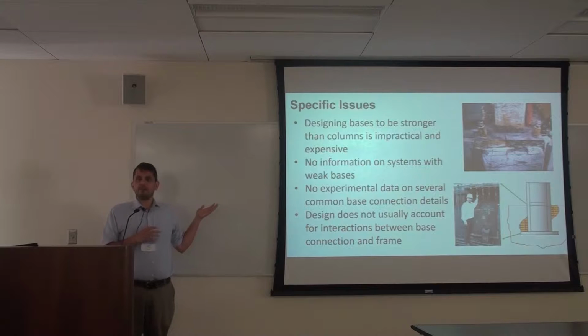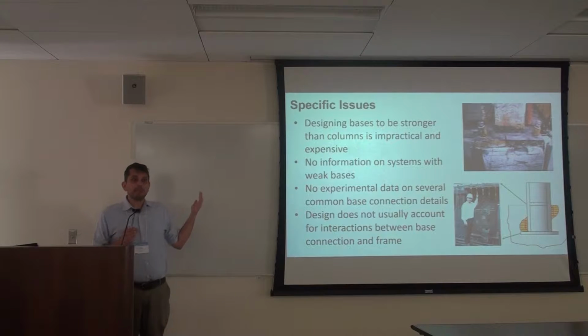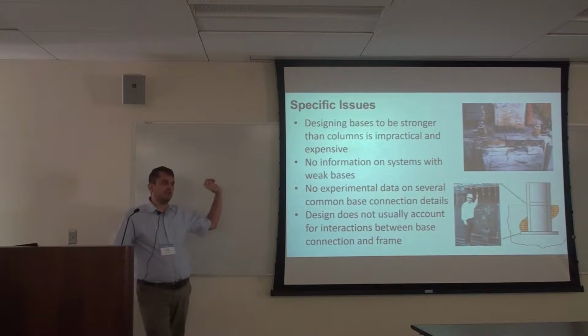And on the other hand, people have been testing steel columns recently, and especially if you have deep columns. Chiaming Wang has tested a bunch, Dimitrios Lignos in Switzerland has tested a few, and the steel columns end up having all kinds of twisting, lateral torsional buckling, local buckling issues at rotations well below the base connections.